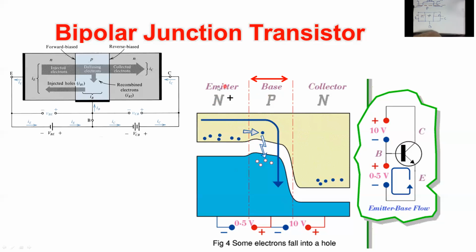This can simply happen by increasing the doping, because you know that whenever you increase the doping, you increase the number of free electrons, whenever it's an N doping. So that's why we use this plus sign in the superscript of N to indicate that this doping is much higher than the doping in the base and the doping in the collector. So these are the two ways where you can decrease or limit or minimize the recombination effect in a BJT or in a bipolar junction transistor.